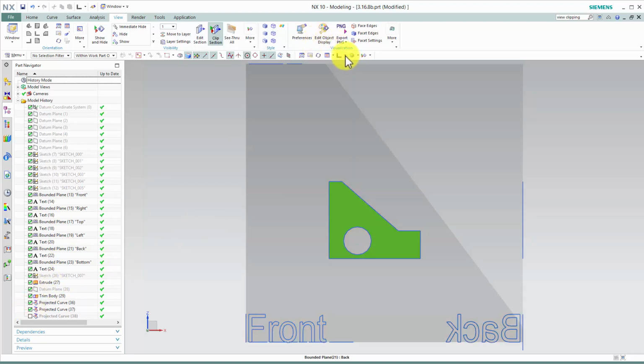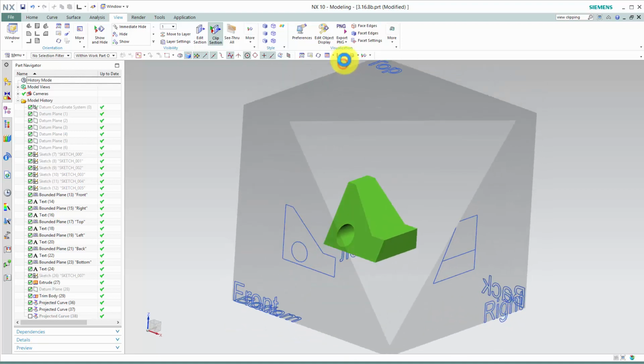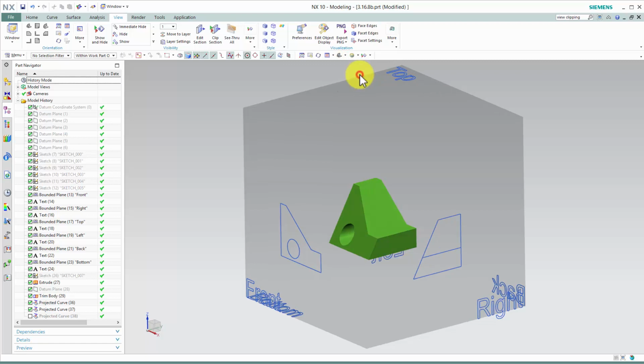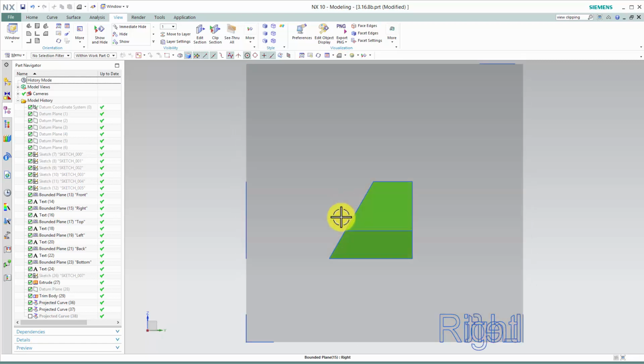In the right side view, we would have this shape, and again, I'm going to turn off the clipping section. We would have this shape, and when we view it from the side, notice how we have the four lines representing the outline or silhouette. We have a fifth line that represents this hard edge, showing the top plane or surface that gets projected out as an edge onto the right side orthographic view.